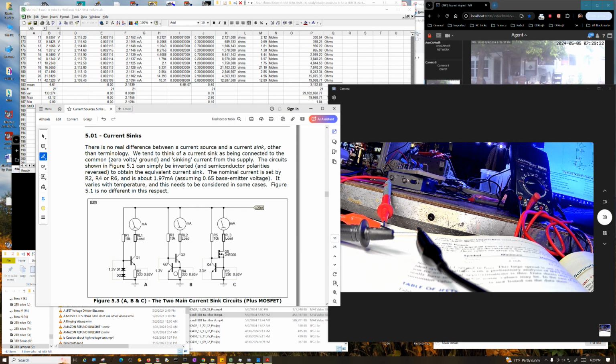Okay. By the way, for example, on a constant current source like this, which is a constant current sink, it basically regulates itself. This part of it is very reminiscent of power supply overcurrent protection circuits you sometimes see. It's looking at the voltage formed across this 330 ohm resistor, and when it's approximately 0.65 volts, that's its limit. That's determined by what current is going through it. In this case, you have about 2 milliamps going through that.